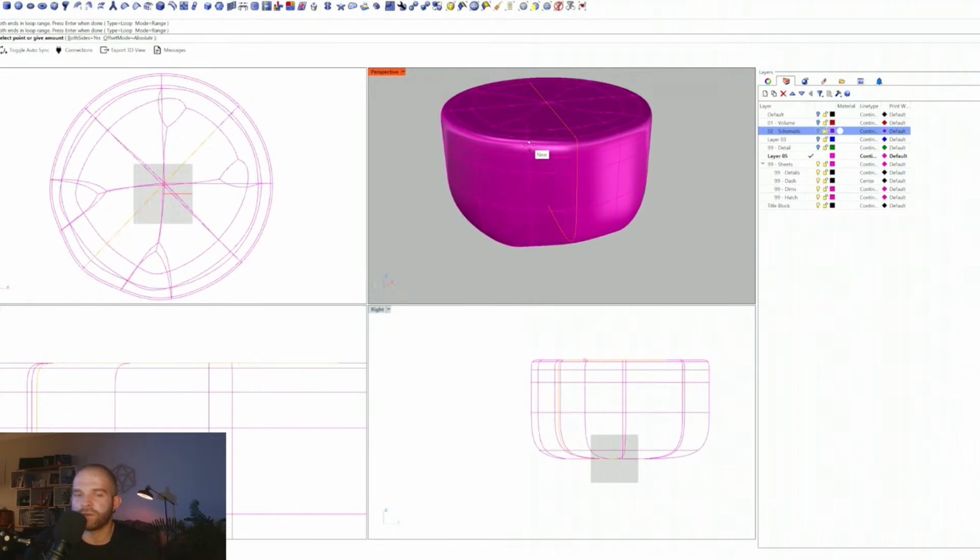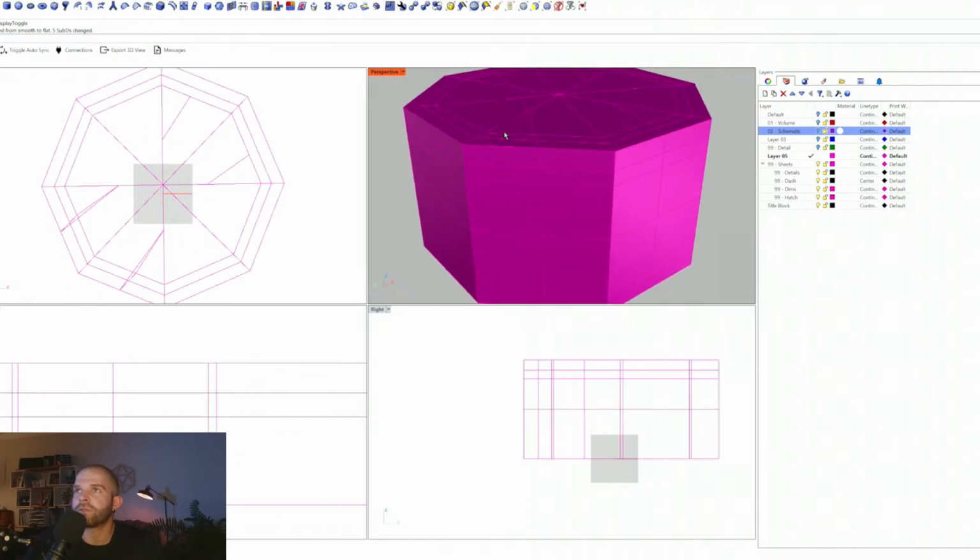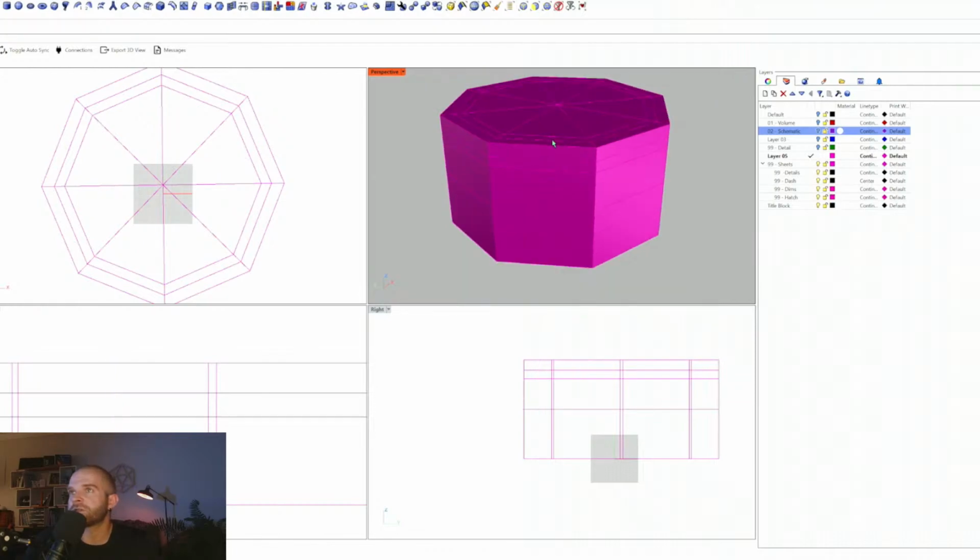We have a triangle face on the top there. And that's what's messing us up. We need it to be all squares. Well, we do have a triangle there already. Okay, so let's do an insert edge from this loop.